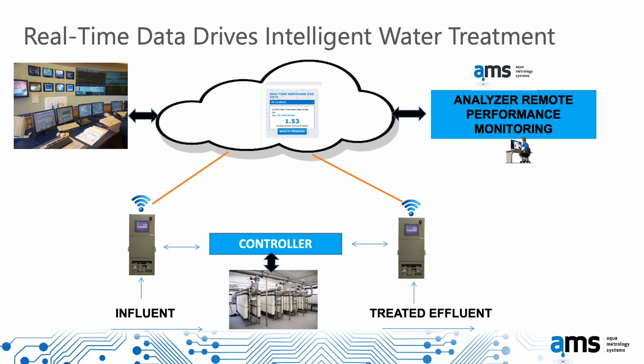Traditionally, treatment system vendors have sold their technology and walked away, happy to lock in recurring revenues from consumables, but leaving behind any guarantees for system performance. That becomes the problem of the utility. Real-time trace metal monitoring represents a paradigm shift in that. As this slide demonstrates, real-time control of influent and effluent can now ensure the treatment system is operating as required or alarm as soon as a non-conformity occurs and before consumers' health is put at risk.